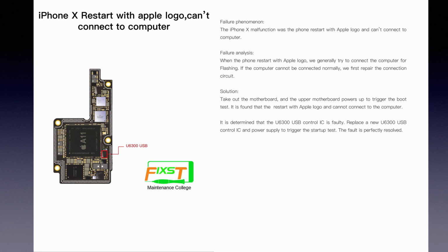This is the iPhone X. It starts with the Apple logo and cannot connect to the computer. When we meet a phone that starts with the Apple logo, we generally try to connect it to the computer and flash it. But now the phone cannot connect to the computer, so we repair the connection circuit first.